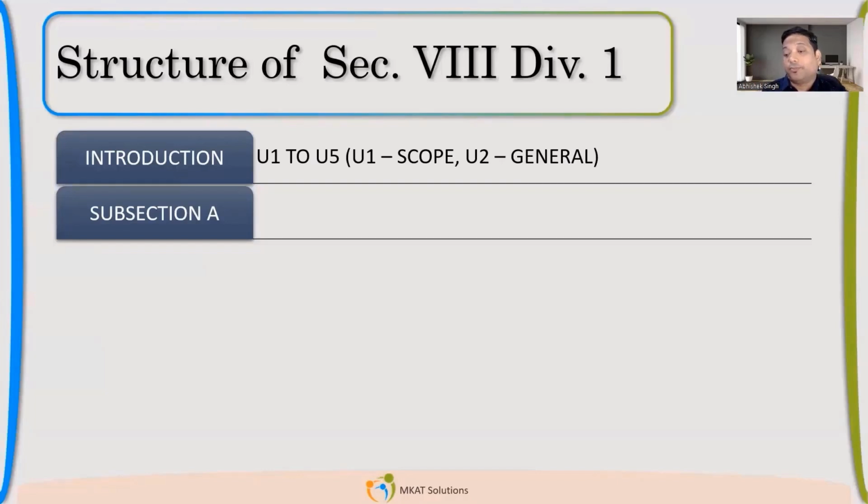So what do we cover in section 2? What are the things which are available in section 2? Chemical plus mechanical properties, steel making practices. Yes, in specifications we'll see that. Allowable stress values, very, very important. That is covered in section 2 part D. Great. Supplementary requirements, dimensional tolerance also, yes, that's there. Material chart for external pressure, yes. So lots of things are there.